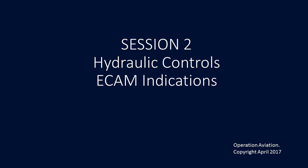What about your hydraulic system memo? The memo messages that you're going to see are on the right side of the ECAM HYD page for the hydraulic system. And what you're going to see here is HYD PTU and also your RAT OUT, right? Your HYD PTU message appears in green when everything's running fine.